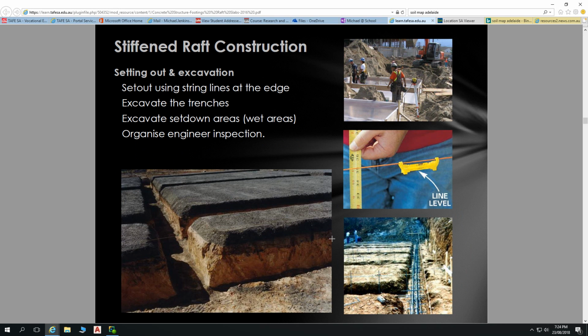This is a particularly neat looking setup for a slab. So what they've done there, they've got some relatively stable soil underneath that, but then they've brought in dolomite, crusher dust, wet that down, compacted it before doing their excavation, and then when they've done the excavation, they've done some very nice, neat batters on the side. That's a very good looking slab.